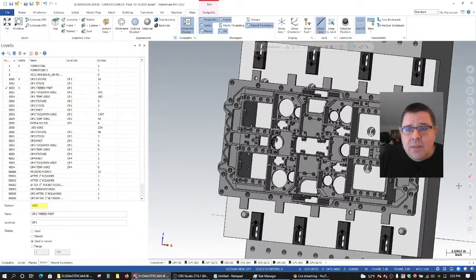So one of the things that I like to do, when I've got a roughing model like this, is to de-feature it as much as possible. I like to simplify the model, which will decrease the amount of calculations that the algorithm will have to perform when we actually go to rough it.